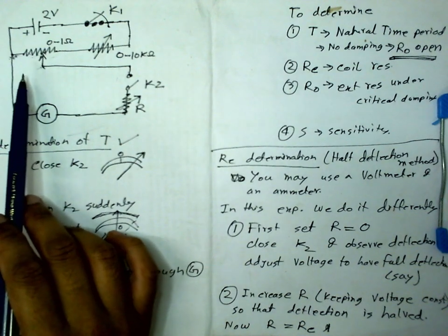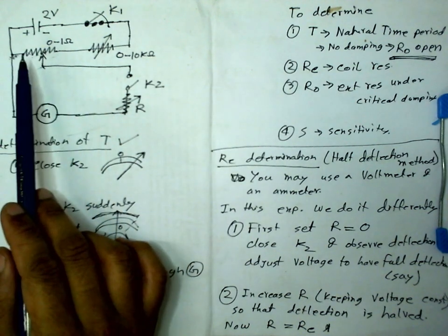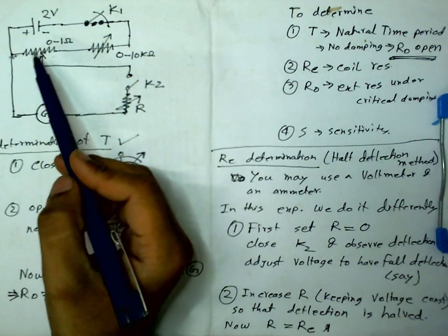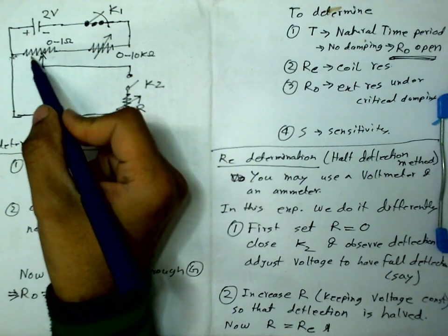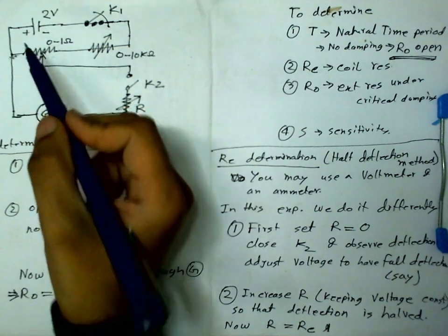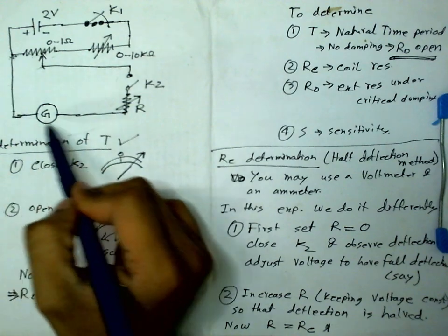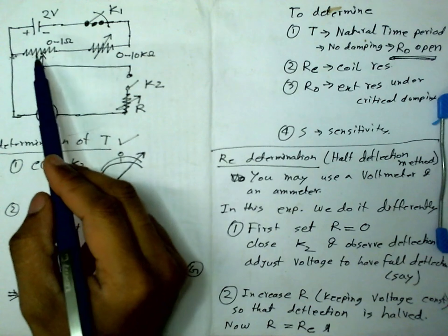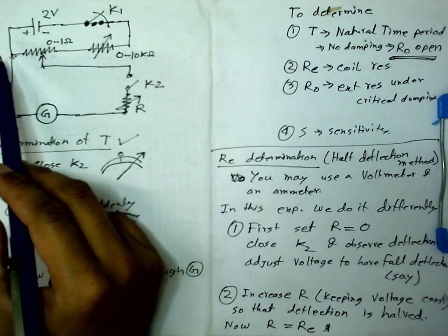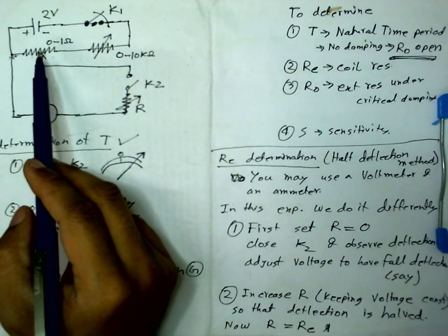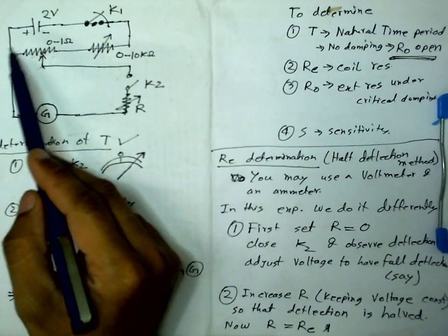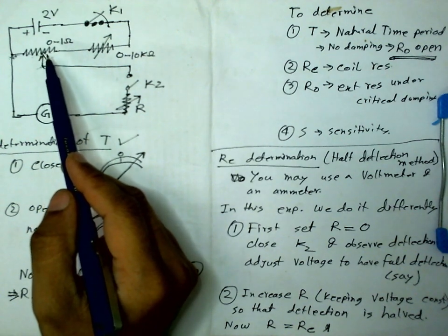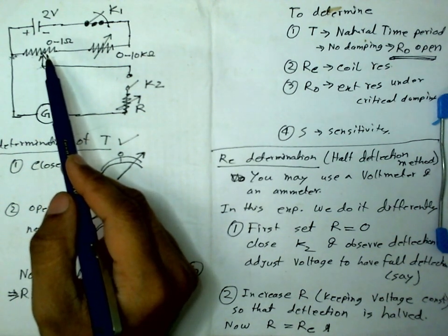In your lab report discussion, you may do this analysis, because when you do this experiment you will know the value of this resistance exactly. You'll also have the estimated values of RC and R, which right now I do not have. At that point you can do an estimation with your calculator: was this voltage really constant, or if not, how much was the change, was it small, was it large.